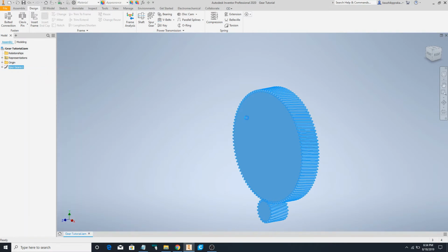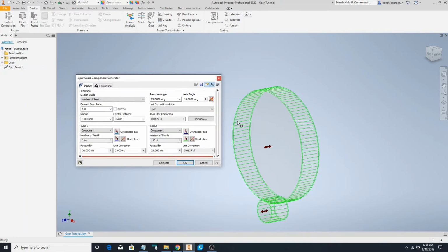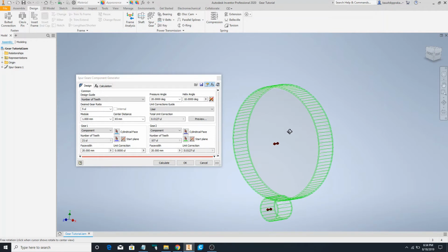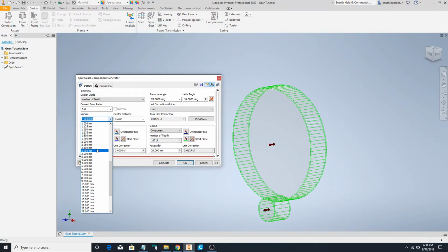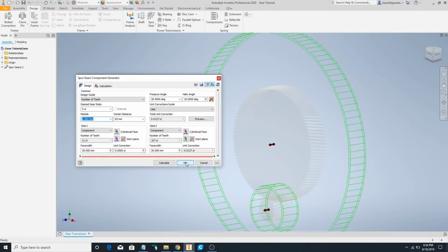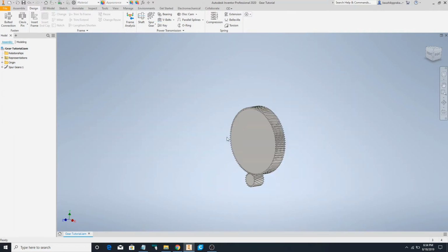This is helpful because if you're machining gears and you want really low backlash and you have high tolerances, then this becomes really handy. But in my case, when you're 3D printing gears, generally 2 millimeters works just fine. But yeah, that's pretty much how it is.